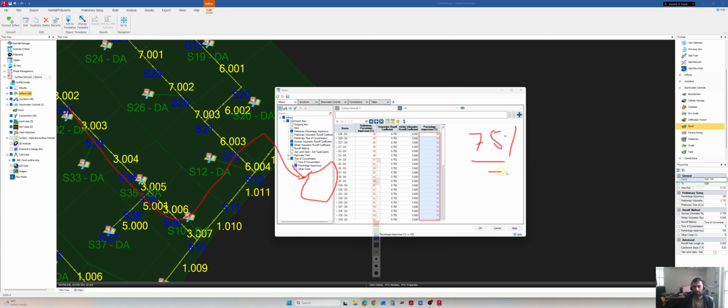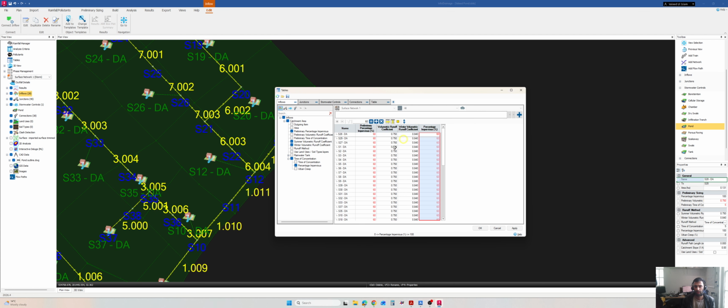And in the winter obviously the surfaces are wet, so the water that goes into the pond is 84%. So these are the values according to that. I'm happy with these values, and we have also updated our percentage impervious values. So I will click OK.